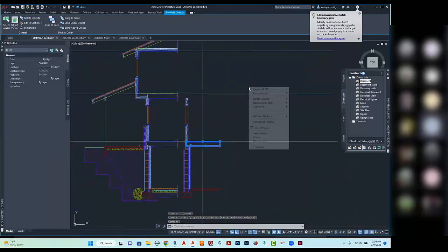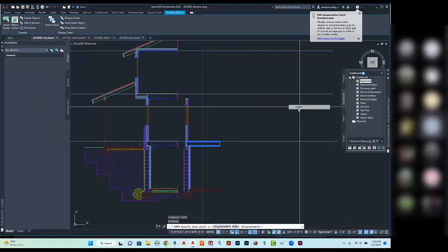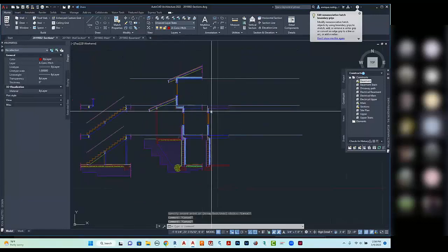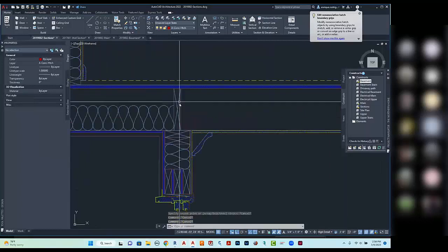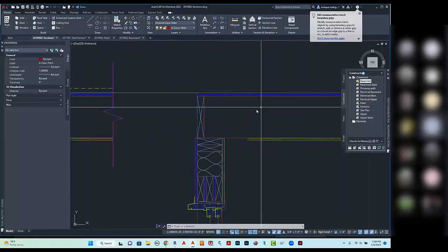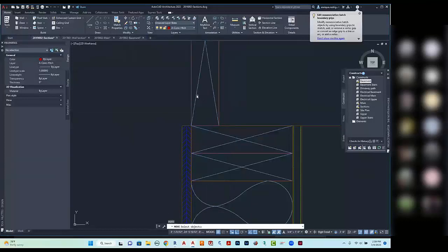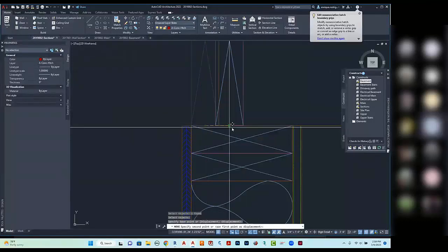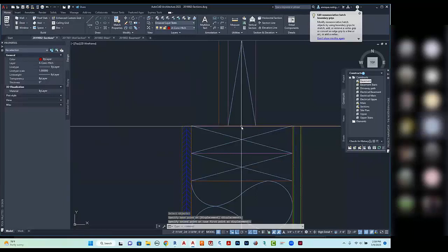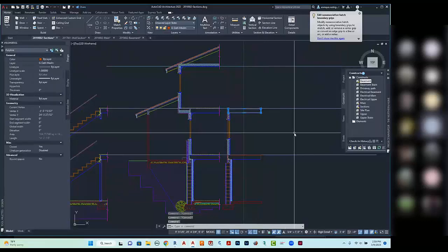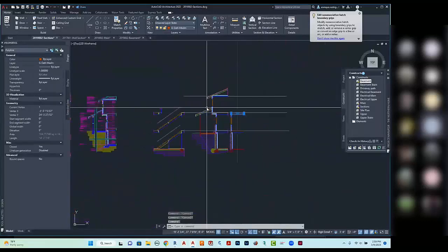So we can take all of those elements, right click, recent input, copy, and we can go from our level lines to our other level lines that we use as a guideline at that point. There's some what we call blocking right here, and we're going to go ahead and center that. Just going to highlight that element and go from here. And again, just eyeball it right in the center, or if you can spot the center point, that's excellent. This 2x10 joist continues 2 feet to the outside.